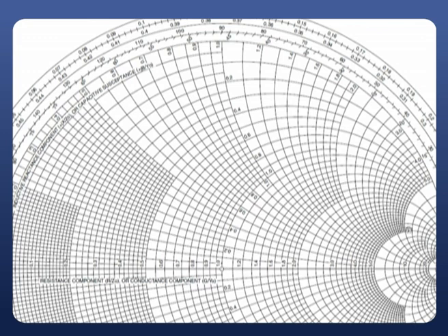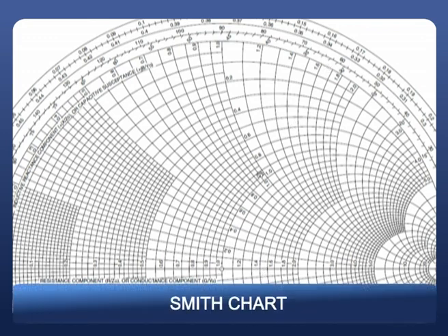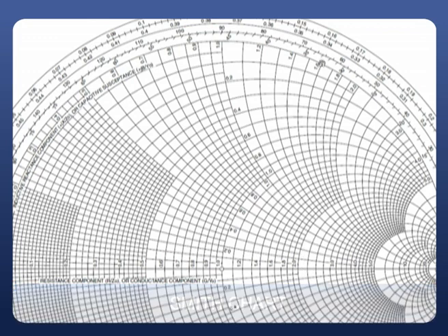Now, once again I will say how to calculate this gamma. Very simple. Just identify ZL, then connect our origin with ZL, extend the line OZL up to point Q, then calculate OZL, calculate OQ, OZL divided by OQ, angle QOS. That angle QOS is nothing but the angle between the line that we have drawn and the real axis in the clockwise direction. This is our simple gamma formula.